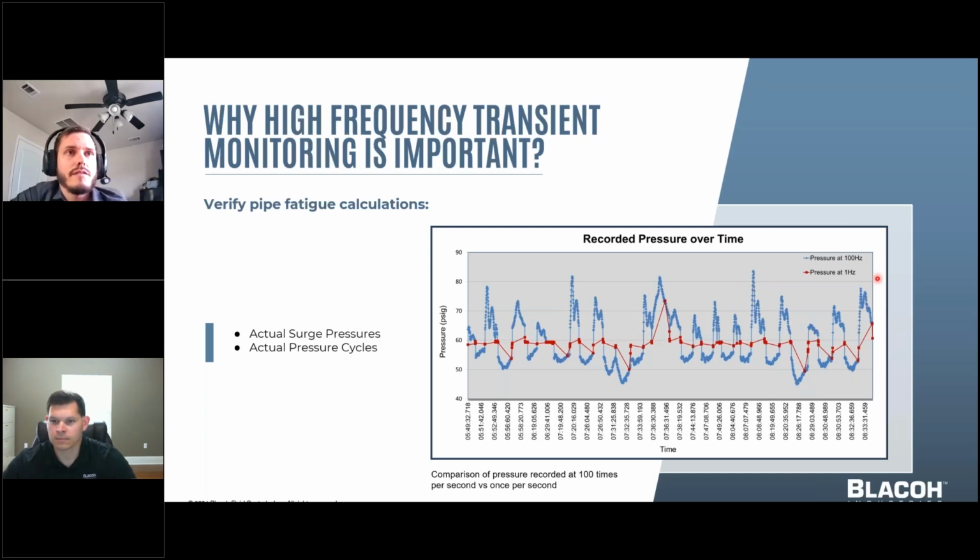Also, the highest of the highs and the lowest of the lows are missed. The space in between the data points are estimated to be linear, which is like the blur you saw in the traffic photos with slow shutter speed. A rate sufficient to characterize the wave for most pumping applications is 100 hertz.